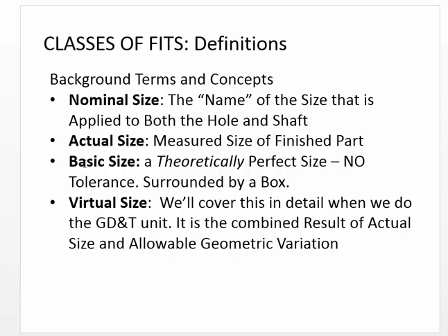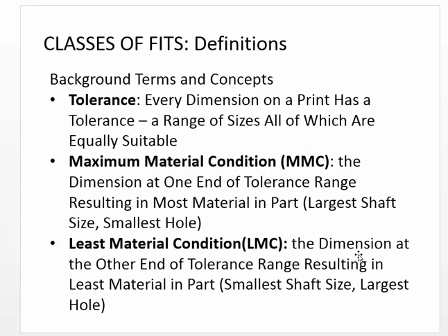Basic size comes into play a little bit. It's the theoretically perfect size with no tolerance, and when you identify that on a drawing, you have to put a box around it. And virtual size we'll get to when we deal with GD&T.